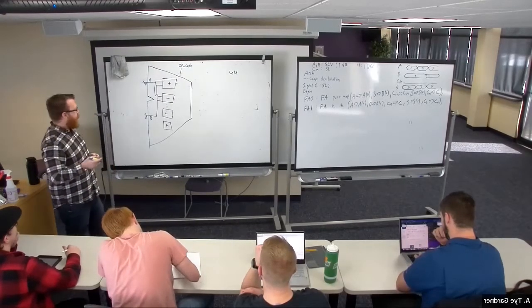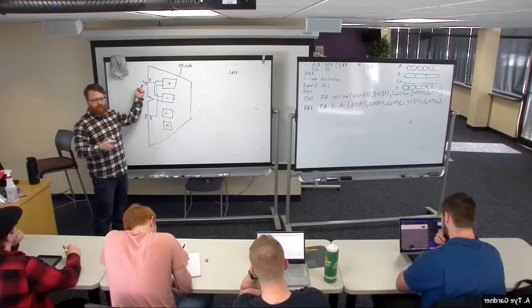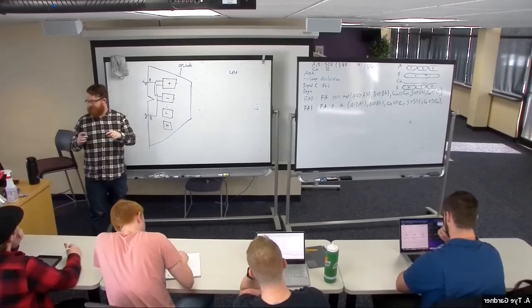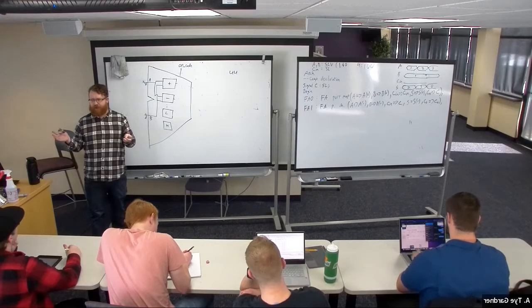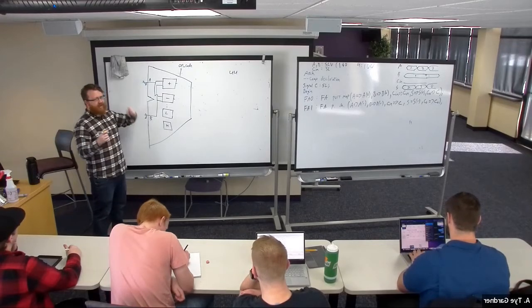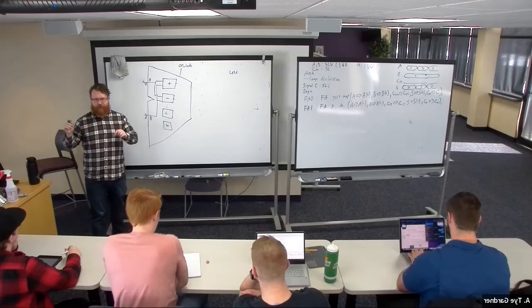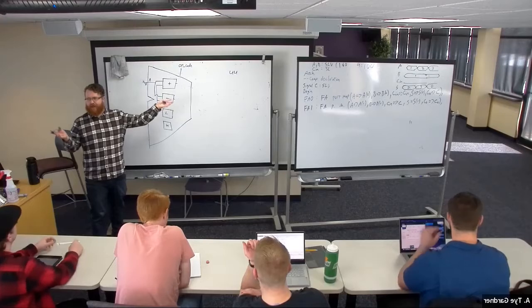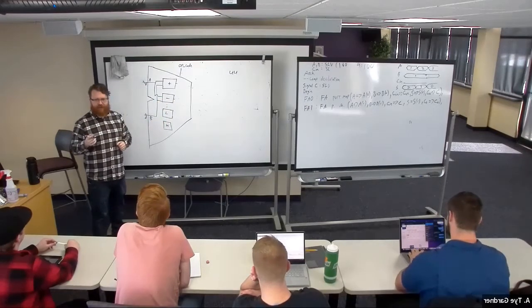Now, our calculator, I have to decide, we're going to build this 8 bits at first. Our board only has enough switches for 8 bits because there's only 16 total switches. So I may come back and have to revisit how many bits we're using in these when I get to the final calculator to put it on the board, but that's a problem we'll deal with later. Right now it's 8 bits. It's not really any more difficult to build 8 bits than it is 4. It's a couple extra copy and pastes.